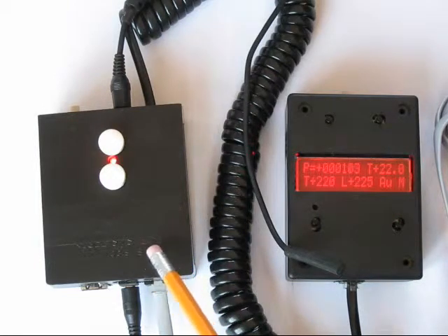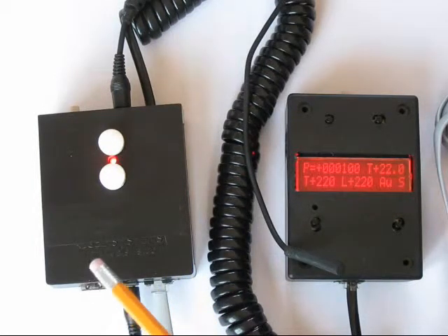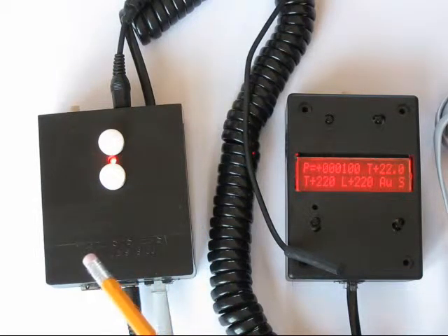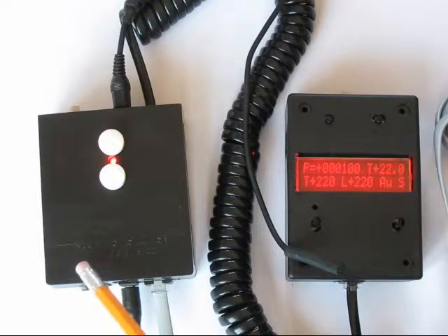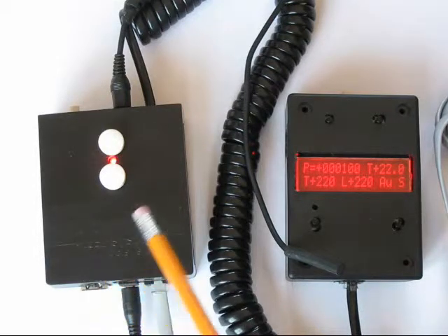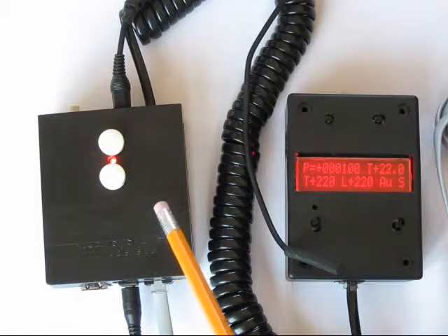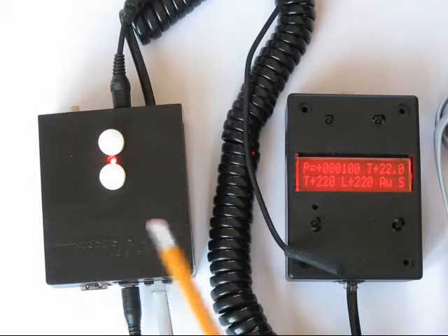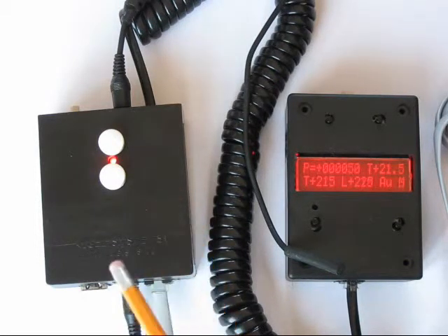I can jumper it for also USB powered, and when you're jumpered for that, it actually opto-isolates between the 12 volt side, motor side, and the PC side, however you want to look at it. That's the safest way to handle it, because you don't want ground loops set up. You don't want ground coming out here, out there, back here. So right now it's set up for that mode.